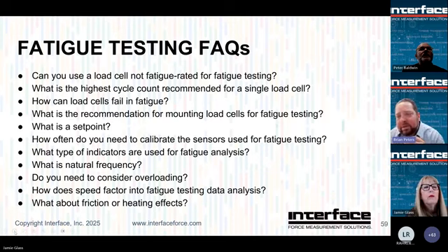And it's just important to pay attention to where you strain relief that. Strain relief meaning you've allowed for an adequate service loop so that if you are translating through a certain amount of motion, you've got a service loop to accommodate that, but you want to have that cable secured if you can. And again, you want to have it somewhere on the dead end if it's a horizontal test, or somewhere on the dead end if it's a vertical, somewhere down below.